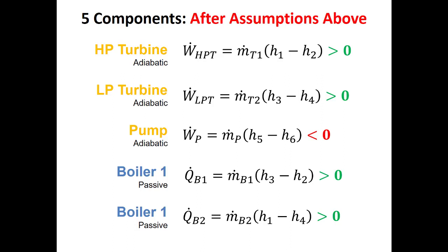So if I was pulling cold water out of, towards the bottom of Lake Ontario where the water is stratified and cold, then I might want to know how much water do I have to pump, right? So it's an important problem to say how much of that cooling water do we need, but it's not a problem that's asked in this particular question. So we're not going to talk about the condenser heat, but if it was here, it would also be m dot times h out minus h in, and we would expect that to be negative.